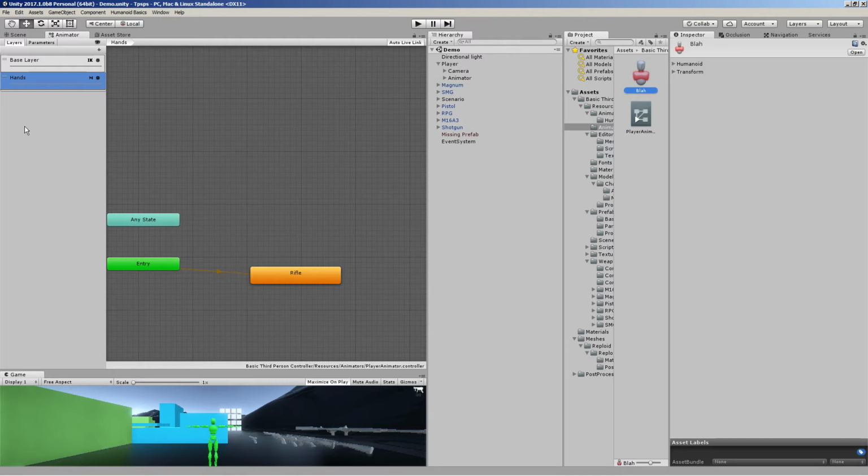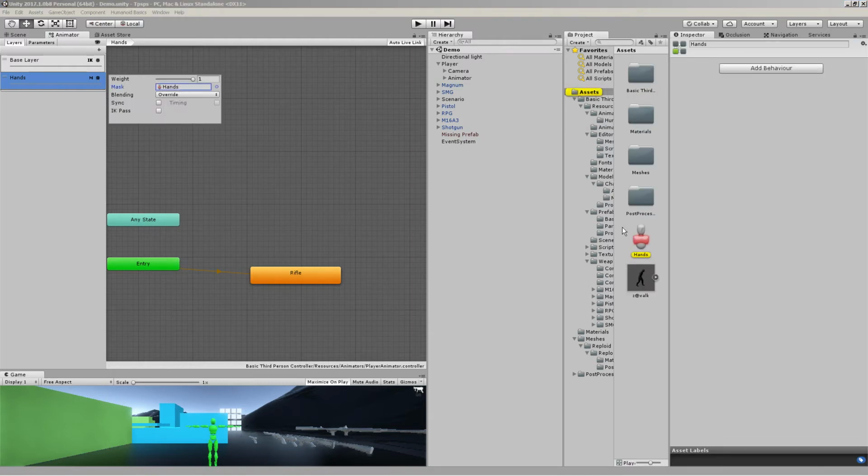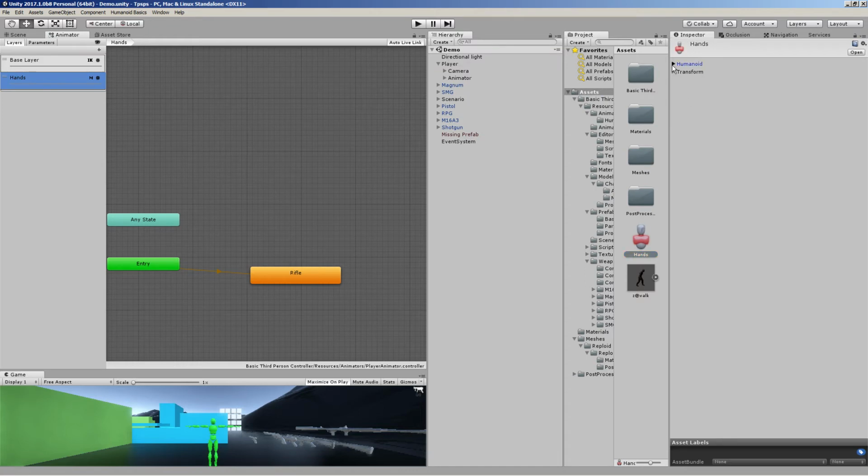And the same thing, once you create that new mask, you're gonna want to just left click, right click, whatever. Don't double click or it'll green out everything. So do it simply, just in between the two IKs here. Just make everything red, and then click the two hands green. Don't screw with the IK, and that's it.